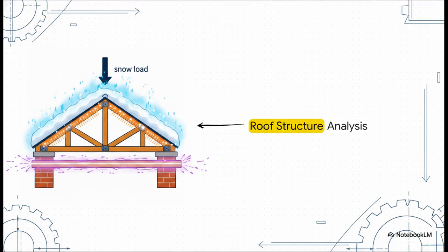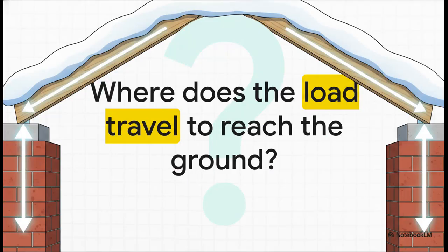The load here, let's say it's a super heavy pile of snow sitting on top. That weight pushes down hard, creating compression on those angled wooden struts. They're literally being squashed. But the horizontal piece running right along the bottom, remember, that's our tie. It's experiencing tension, pulling super tight to stop the bottom of the roof from just spreading completely apart under all that weight.